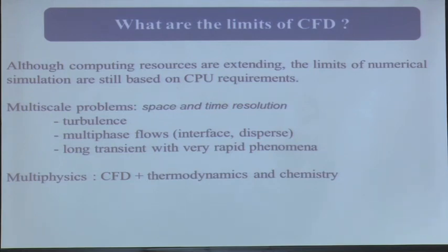So you need a large domain, but if the flow is turbulent, the Kolmogorov scales are very small, and you need to resolve them also. So you need grid points with delta x similar to the size of the smallest eddies. If you have a very small grid and a large domain, then you are going to end up with billions of grid points, and that will be very time consuming to get the solution. It's very simple to understand, but still we don't know how to correctly model turbulence.